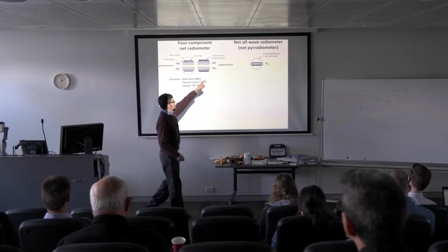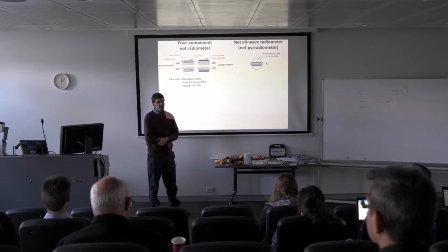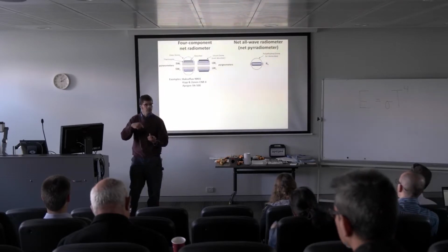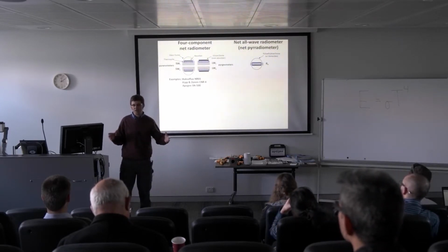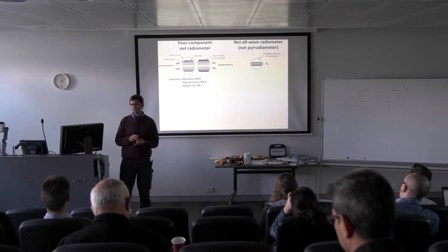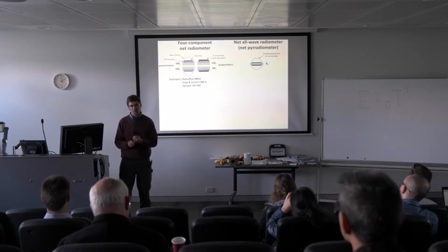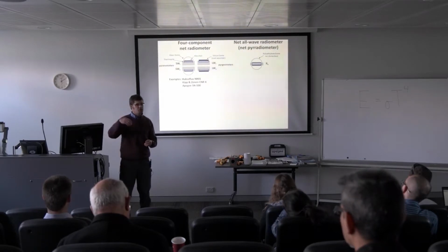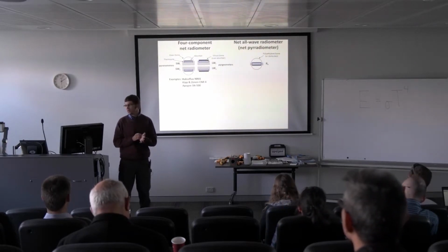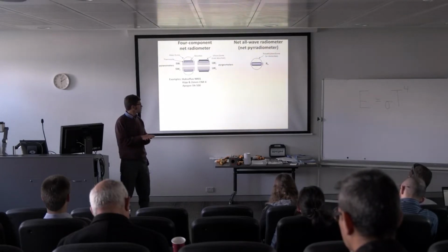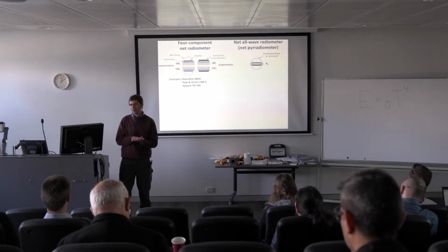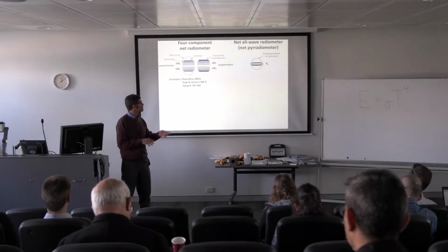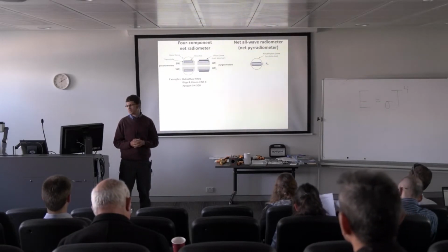The reason this is called a net all-wave radiometer is that each surface, the upward-looking surface and the downward-looking surface, is measuring all of the wavelengths at the same time. So it's sensitive to shortwave and longwave together. Polyethylene actually transmits shortwave and longwave. And the reason for the polyethylene domes is basically to be a weather barrier and keep rain and moisture and dust and dirt off of the black body surface.